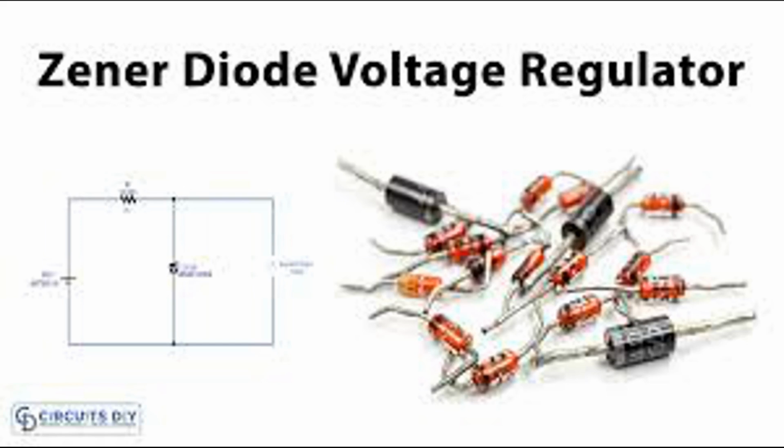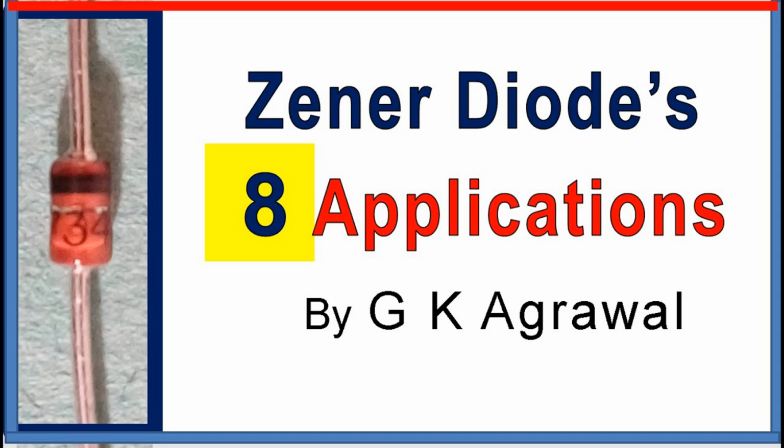Practical considerations. Heat dissipation. Ensure that the Zener diode's power dissipation does not exceed its rated value to prevent overheating. Series resistor. A series resistor is typically used to limit the current through the Zener diode, ensuring it operates within its specified range. Circuit design. Careful selection of the Zener diode and series resistor values is crucial for effective voltage regulation.